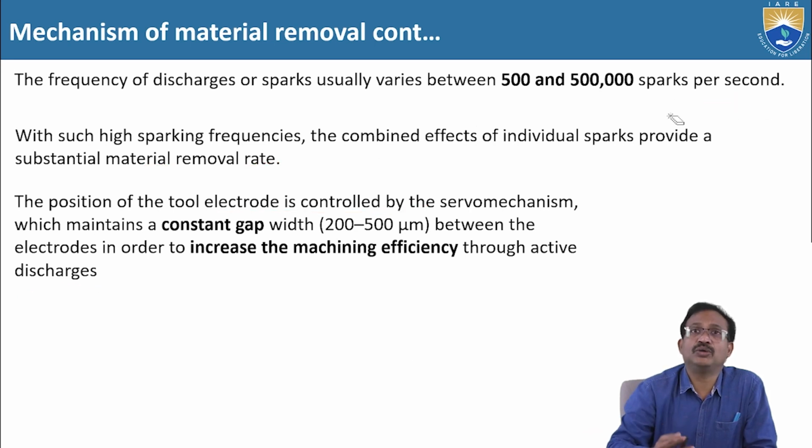Here the tool will move down, with no lateral directions. But the workpiece, which is fixed on the fixture and mounted on the table, will move in X, Y and Z directions.